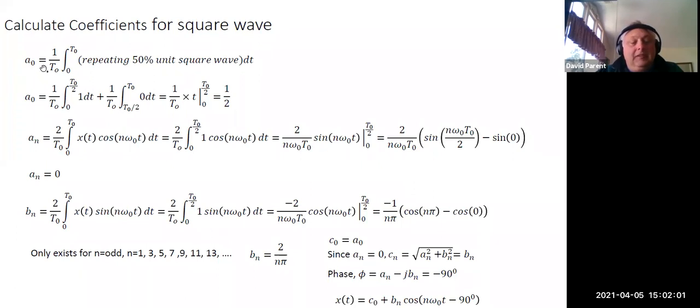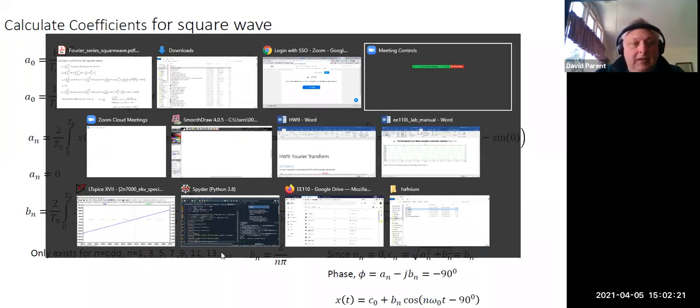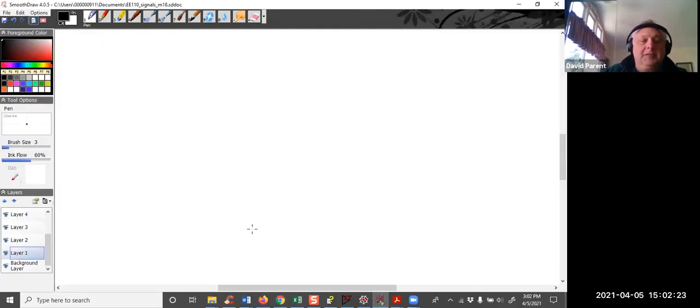So what is the DC offset? Remembering it's the average of the waveform. In this case, it's a 50% duty square wave. So plugging that into the equation, it's actually discontinuous. Let's just double check that we remember what a 50% square wave is.